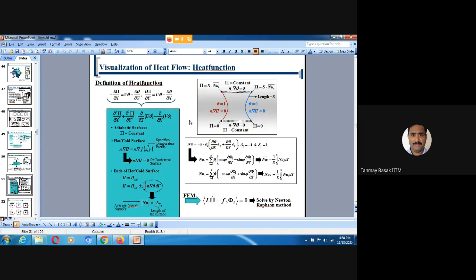So although the heat function will have the structure of a Poisson type differential equation, it will have complicated boundary conditions, which can be derived from the Nusselt numbers. We'll have the point type Dirichlet condition, we will have the wall Neumann condition, and in fact this kind of system has over specified boundary conditions, which will even make people struggle to understand how to implement the boundary condition.